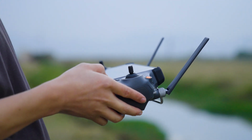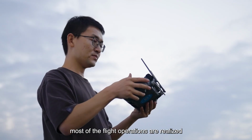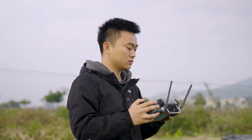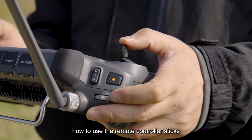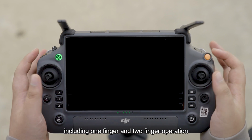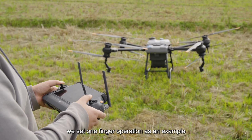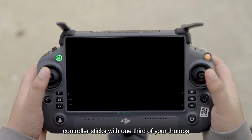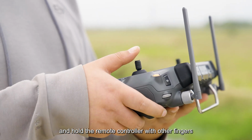Remote controller. Firstly, it is the introduction of the remote controller. Most of the flight operations are realized by using the remote controller sticks. Below is a video for that. Firstly, we will explain how to use the remote controller sticks, including one-finger and two-finger operation. We set one-finger operation as an example as it is relatively easy to use. Press the remote controller sticks with 1/3 of your thumbs and hold the remote controller with other fingers.